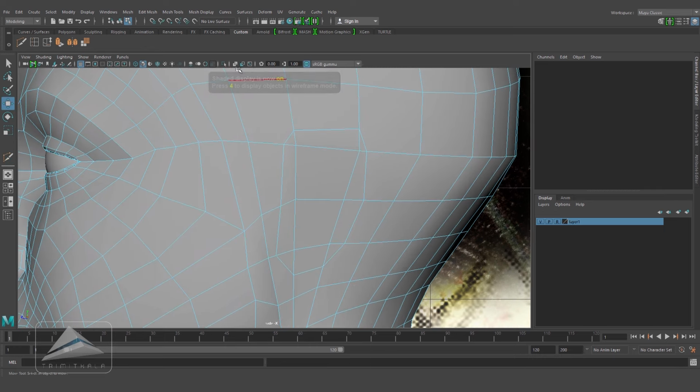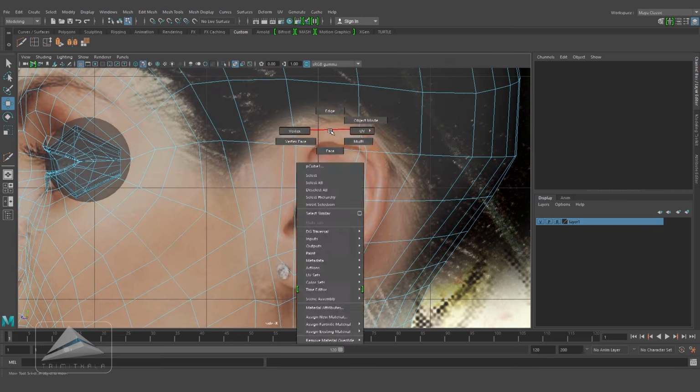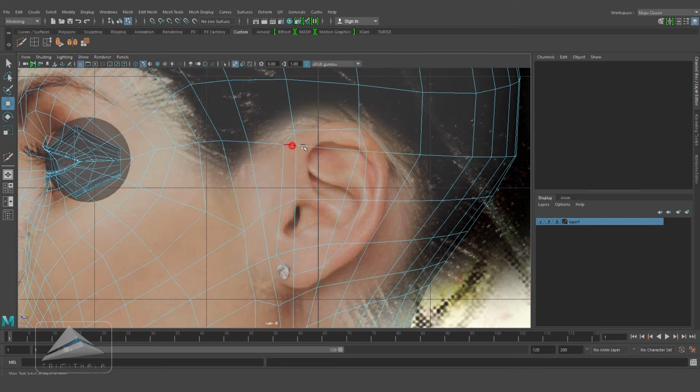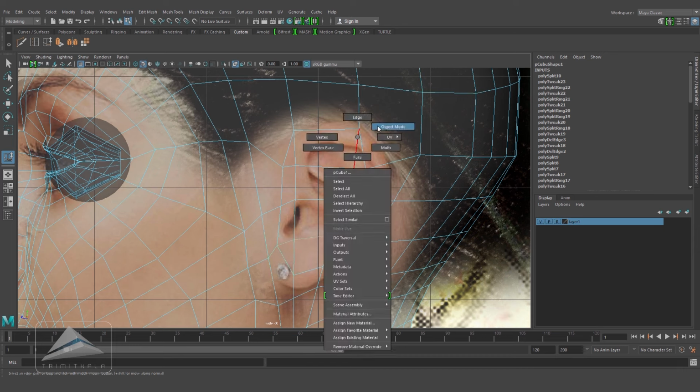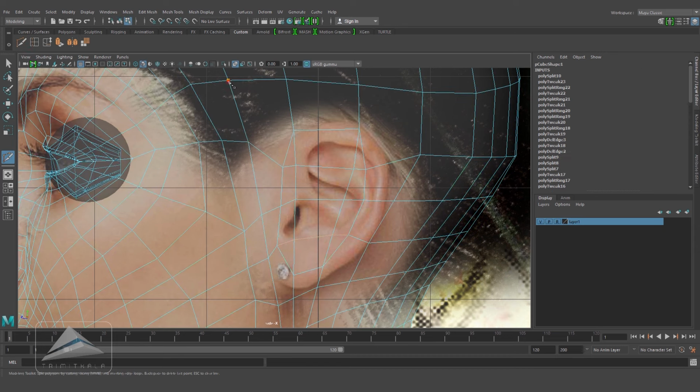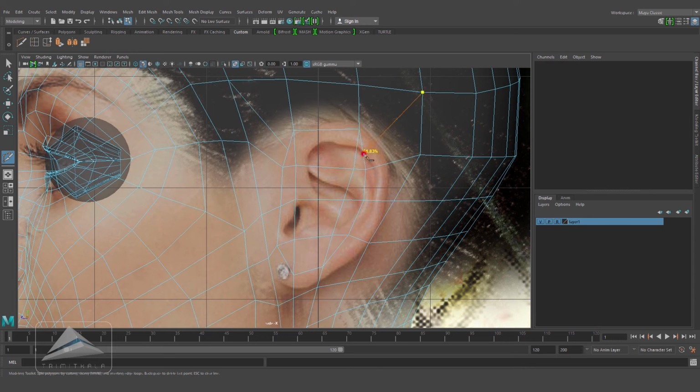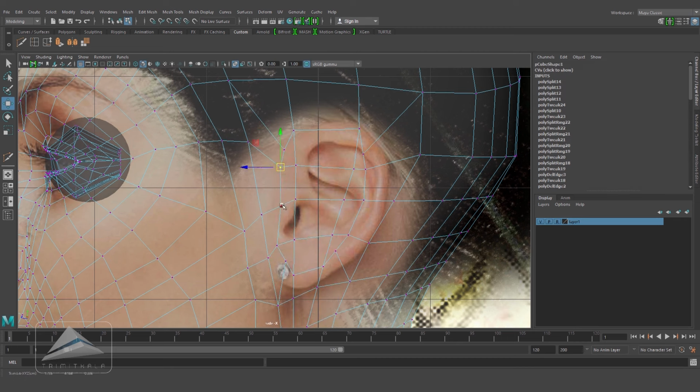Little bit adjustment by selecting the edges, and all the four corners you can see I have created 4 pentagons and 4 triangles, so that also I need to split and I have to rectify it. So from the corners up to the triangle I am splitting it for all the 4 sides, and now you can see everything is quads. So now once again by selecting the vertices I am equalizing it.